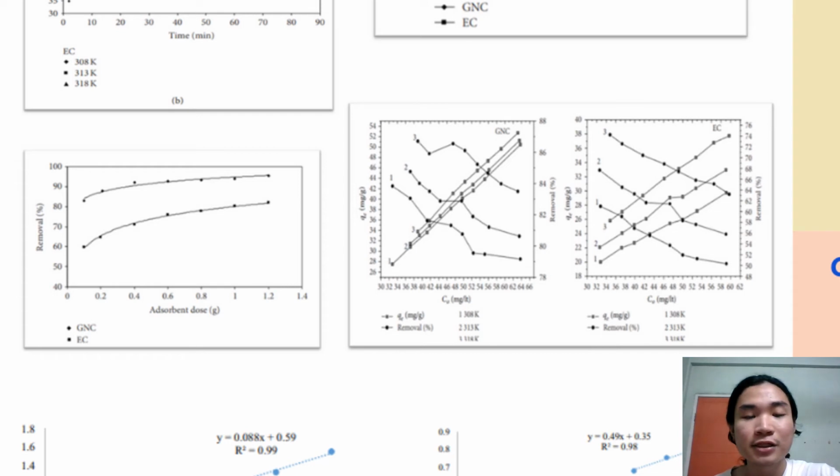as the initial concentration of dye increases, the equilibrium adsorption capacity increases too. More adsorbate molecules are available to be adsorbed, so the actual amount of dye that is adsorbed on adsorbent surface rises too. Meanwhile, the removal efficiency decreases as the initial concentration of dye increases. The active sites of the adsorbent surface become saturated, hence slowing down the adsorption and ultimately reducing the removal efficiency.